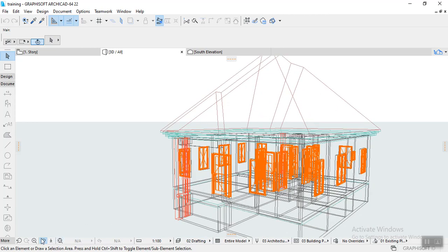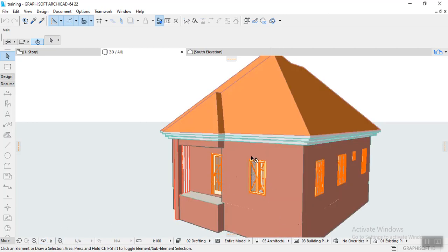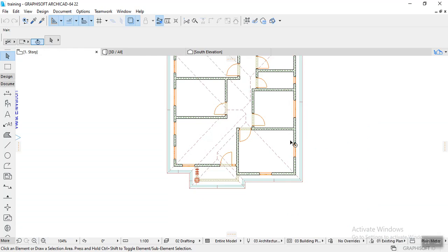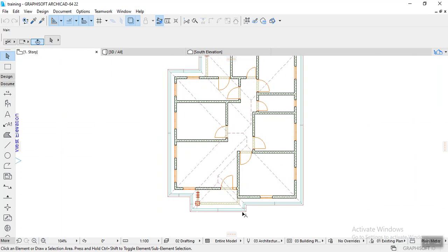So that being done, let's put in our wall extra first. I'll go down to my ground floor. I want to add my wall extras on this, and all the windows. So what I'll do, I'll come down to my design. Don't forget I'm using Archicad 2022 and it's applicable from 2022 downward.